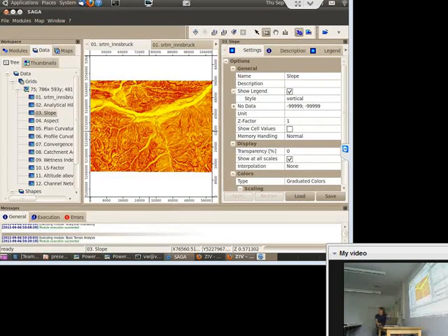you will report the actual values, and you will see that you have now 0.5 and stuff like that. So in case you do a reclassification of this grid, or you like to compute with this grid in the grid calculator, be aware that it is actually radians. Otherwise you will create a lookup table, for example, for slope classes 0 to 5 degree, 5 to 10 degree, and you will wonder why it is not working, because the actual values are stored in radians.